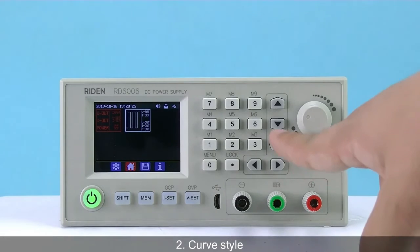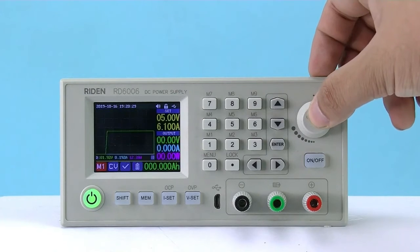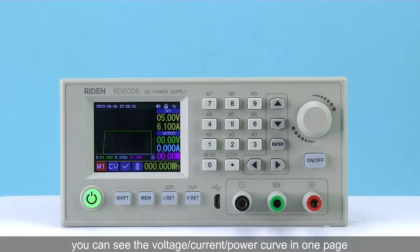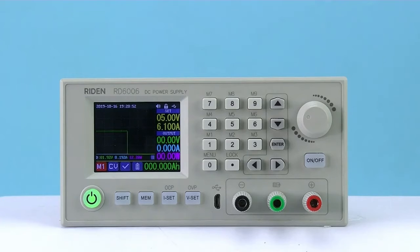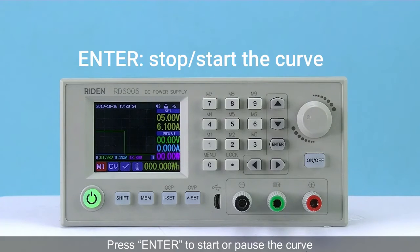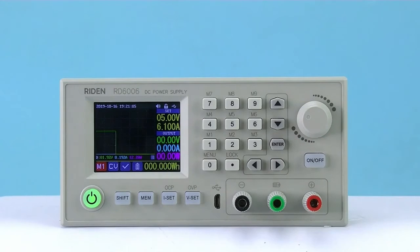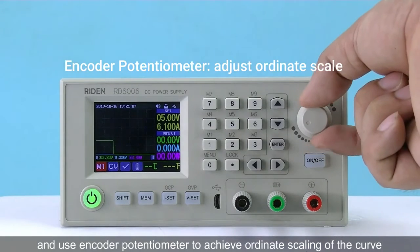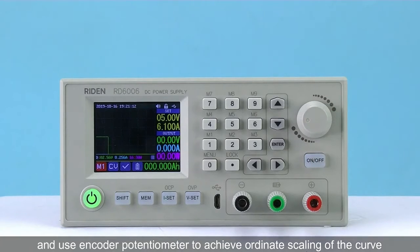2. Curve style. You can see the voltage, current, power curve in one page. D is the scale of the ordinate. Press Enter to start or pause the curve. And use the encoder potentiometer to achieve ordinate scaling of the curve.